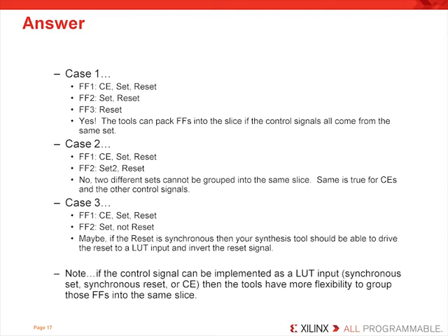And in our third case, the answer is maybe. If the reset is synchronous, then your synthesis tool should be able to drive the reset to a LUT input and invert the reset signal to get this to work. Note, if the control signal can be implemented as a LUT input in the case of a synchronous set, synchronous reset, or a clock enable, then the tools have much more flexibility to group those flip-flops into the same slice. So, what do you think the lesson is?